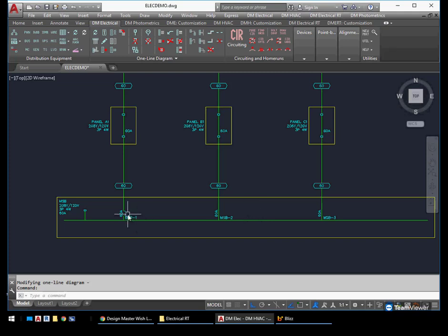It did not copy over our breaker there, I think because we have the breakers turned off. So in this case, we'll use the match labels and graphics, and I think that will pull it over, and that does. So it did lose that graphic, and it shouldn't have, but we can add it in there. And now, of course, as you continue to make changes to your design, if you make changes to any of those, all the labels will update as appropriately with those panels.